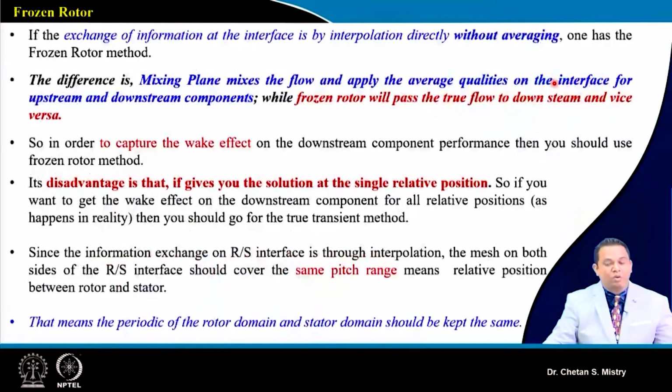Okay. Now in order to capture flow separation, secondary flow, and wake formation, we need to go with a different approach, called the frozen rotor approach.